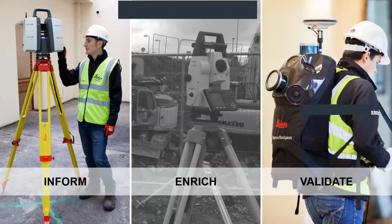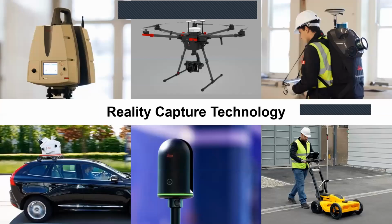And once the site is constructed, you can go with a mobile mapping device and do a validation, depending on the size of the project. If the project is small, like a shopping mall, you can go with BLK. If you have constructed a 100 meter road or a big shopping complex, you can go with a mobile mapping solution, and then you can validate those structures.